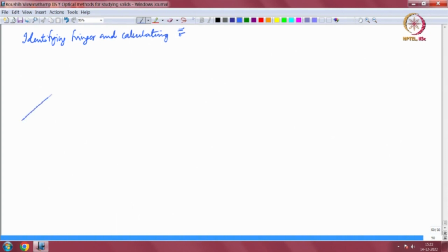The first is this idea about using the polarizer and the analyzer. Remember, both of them are just polarizer sheets. If you use them in the form that we discussed, I mentioned at the start of today's session that this is called a dark field image. What you see here at the end is a dark field image, and a dark field of course is because in the absence of any stresses, in the absence of any birefringence, you will get a black image.